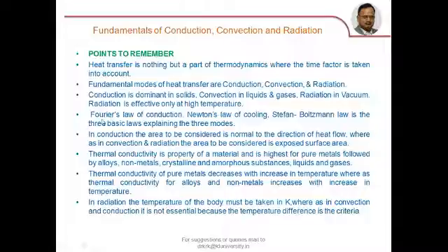Conduction is governed by Fourier's law of conduction, Q equal to minus K A dT by dx. Convection is governed by Newton's law of cooling, Q equal to h A delta T. Radiation is governed by the Stefan-Boltzmann law, Q is equal to sigma A T to the power 4. These are the three basic laws explaining the three different modes of heat transfer.